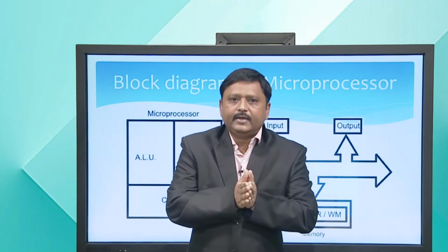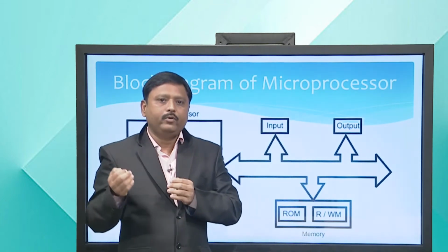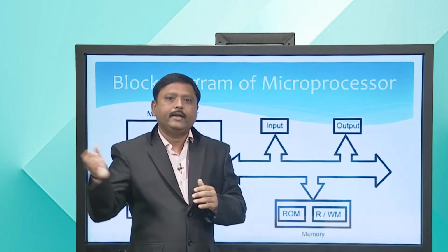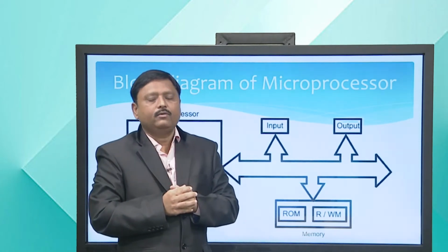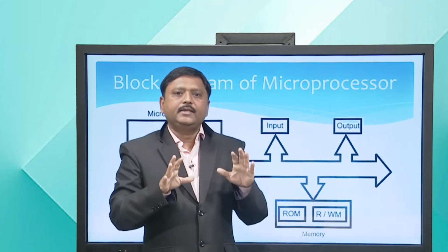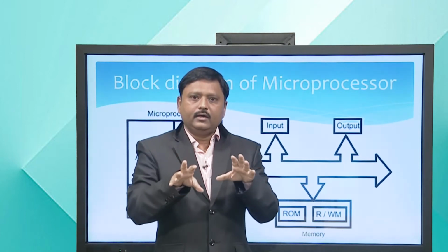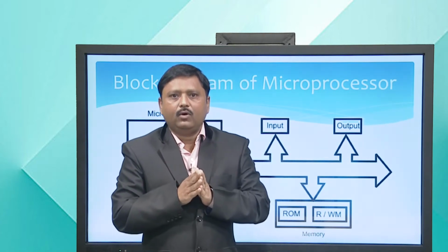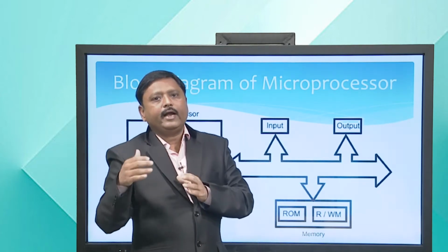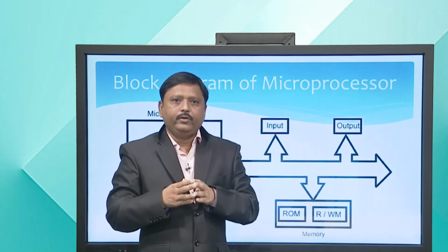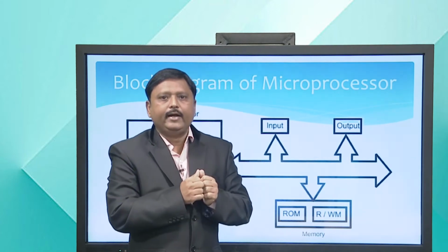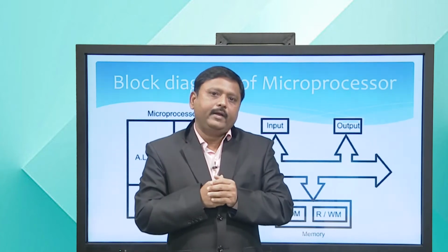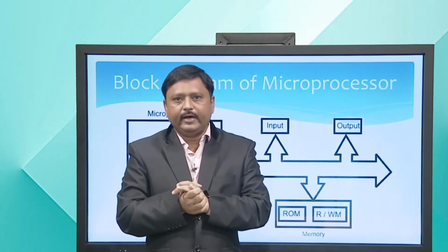Monitor program reads instructions received from input, compares with the standard set and provides the equivalent binary code to the processor for execution. So, basically the monitor monitors the entire activity of the microprocessor. On the other end, read write memory is user memory. The user can save his program and data in read write memory or RAM, and the content of RAM can be edited because it is a read write memory.